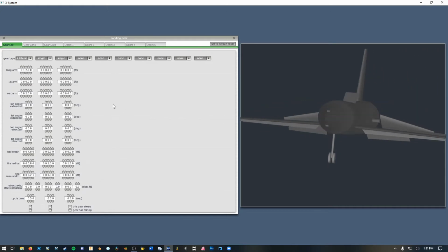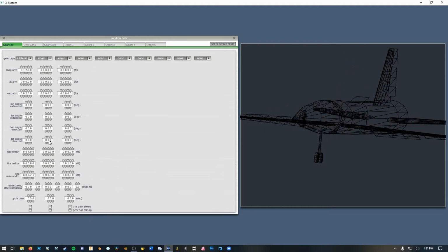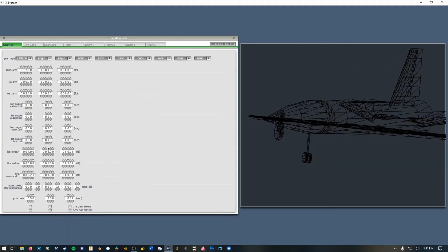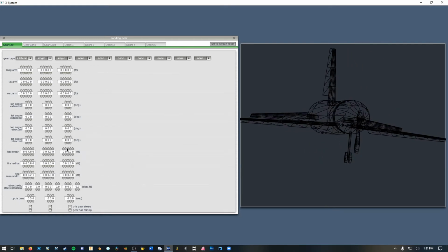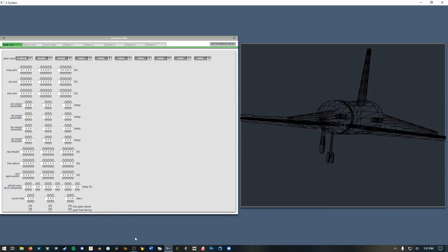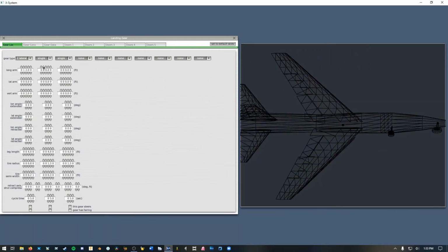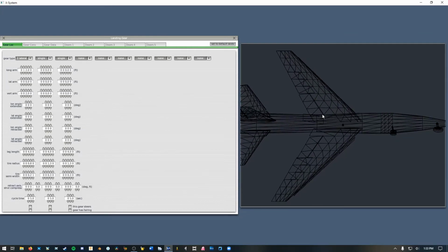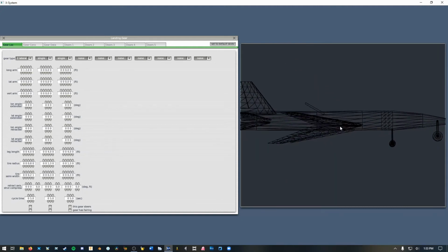Now I'm just going to do the main landing gear. So for these, I'm going to give them a leg length of 5, no, let's just do 4 feet for these as well. Right, so now that I've created a leg length for each of my main landing gear, I'm going to position these as well. Except now for the main landing gear, this is a pretty important step. You want to position them so they're just behind your center of gravity, so that when you rotate your aircraft, it'll rotate on your main landing gear.